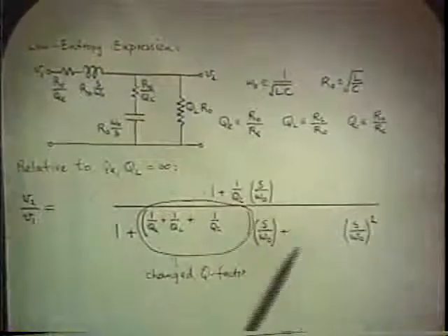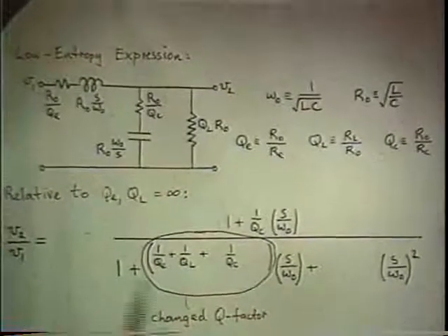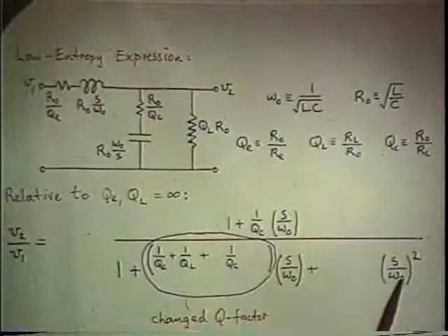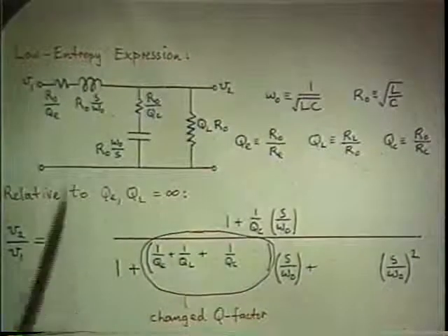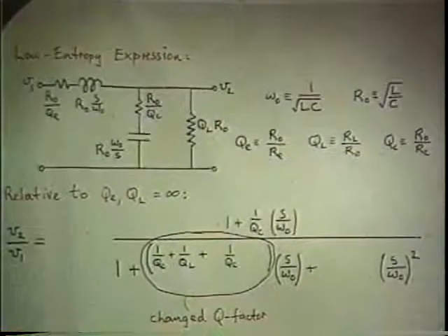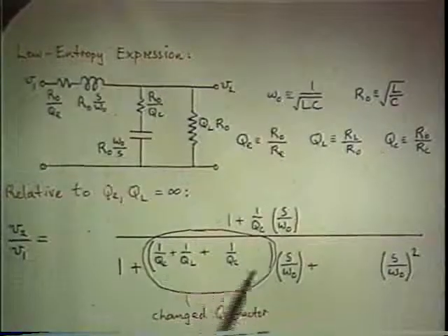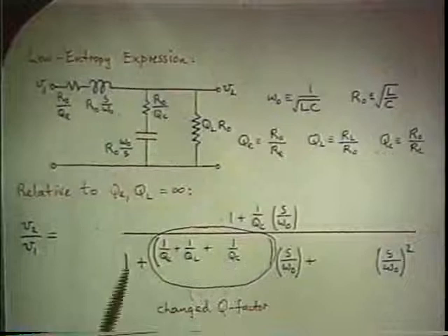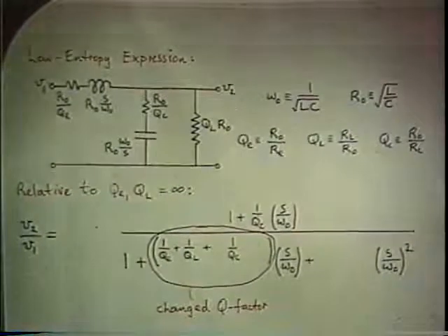Now, it hits you right away what the property of that circuit is. It's a straight quadratic in the denominator, no significant change of corner frequency, no significant change of zero frequency response. There is a change of total Q factor, which is the entire middle coefficient. But look what happens.